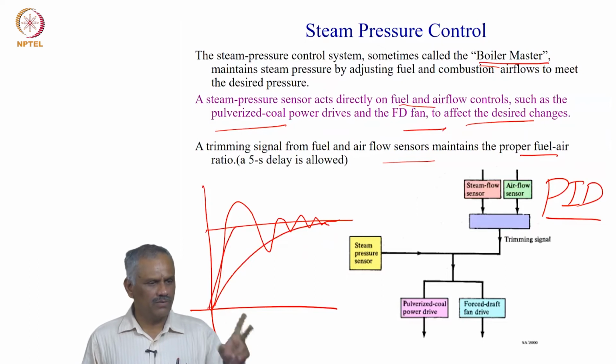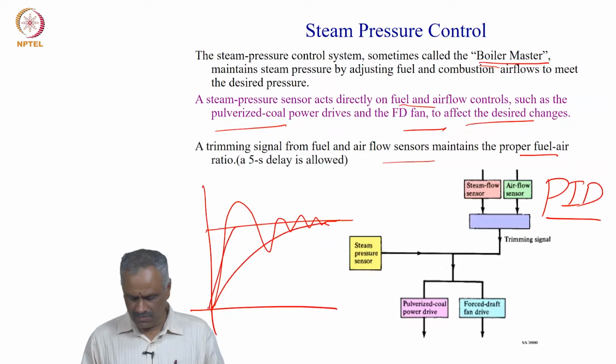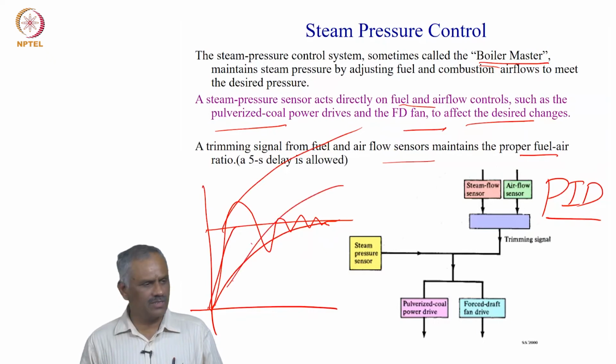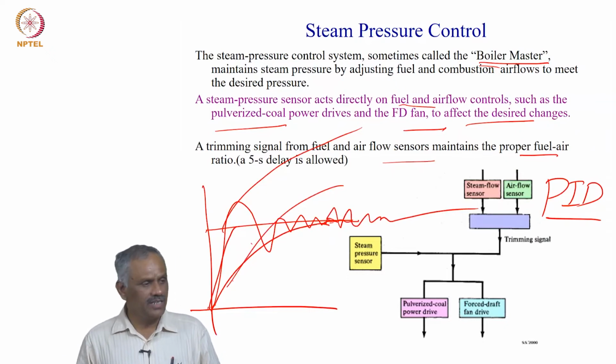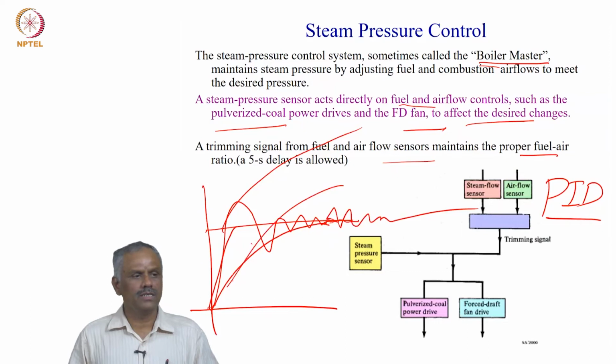It should reach stability, because it should not overshoot and go away from the set value. Second, it should be accurate, close to whatever is set. If it gives a higher value, though it has become stable, it never reaches the accurate value; it just fluctuates and takes infinite time to reach it. So: stable, accurate and fast. We study control systems mainly for this reason.